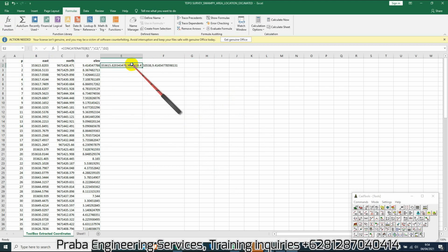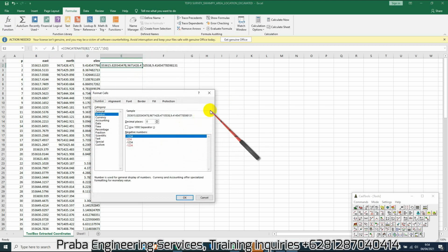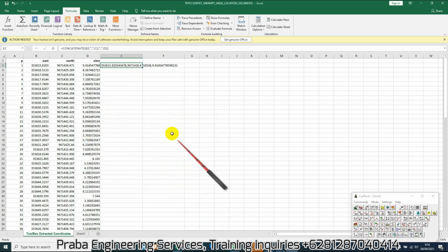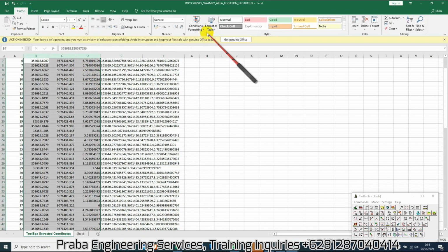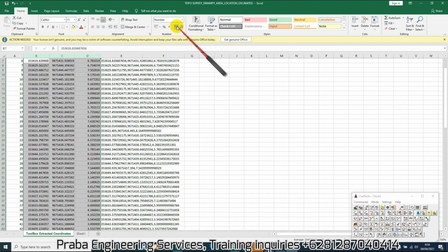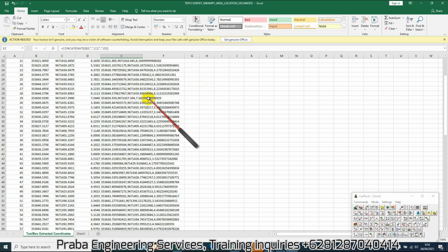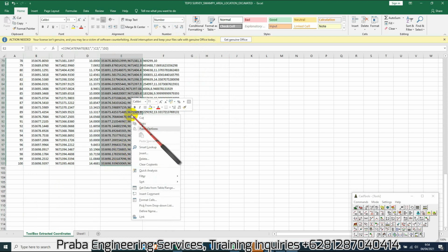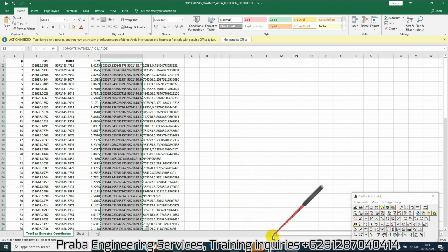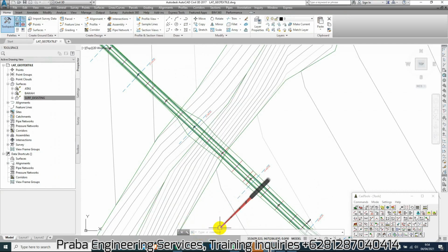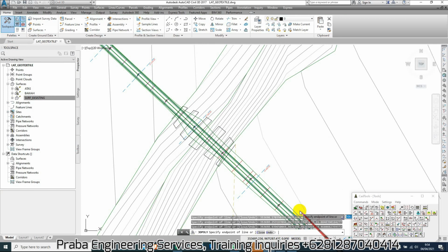Okay, after you change, you need to check the formula cell. Sometimes they still have the tag, you can change it by the number. Okay, make it somewhat more tidy by clicking the 0, then lock all the rows in here, go to Civil3D and we plot in Civil3D again by 3D poly. Then click in the command bar, paste.